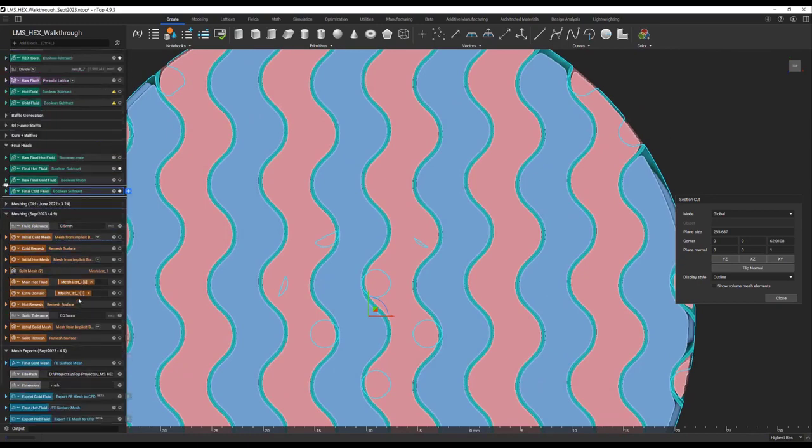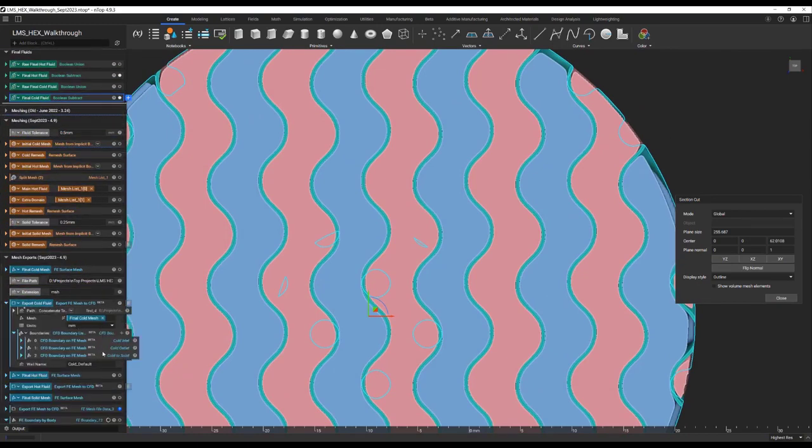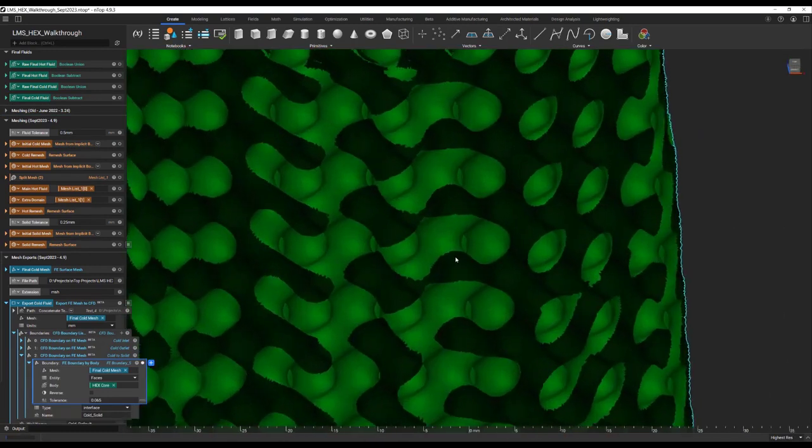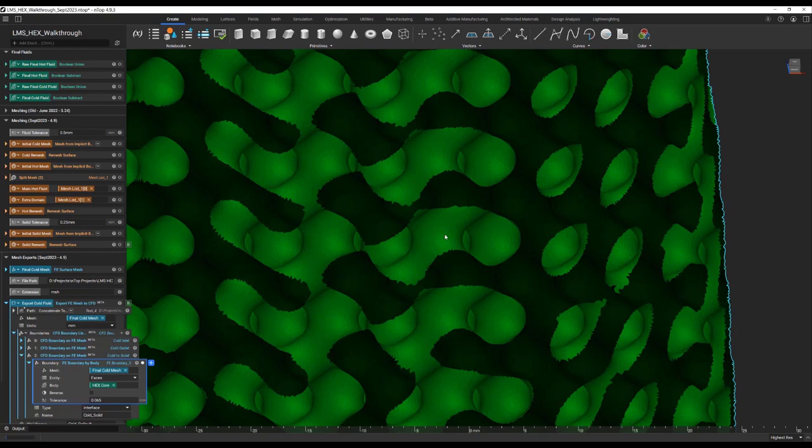What that means is when I come to generate my interface regions, there's going to be some overlap between the two objects, between the two meshes. And when we pull these into ANSYS, it sometimes gets a little bit confused on what boundary zone is associated with what object.